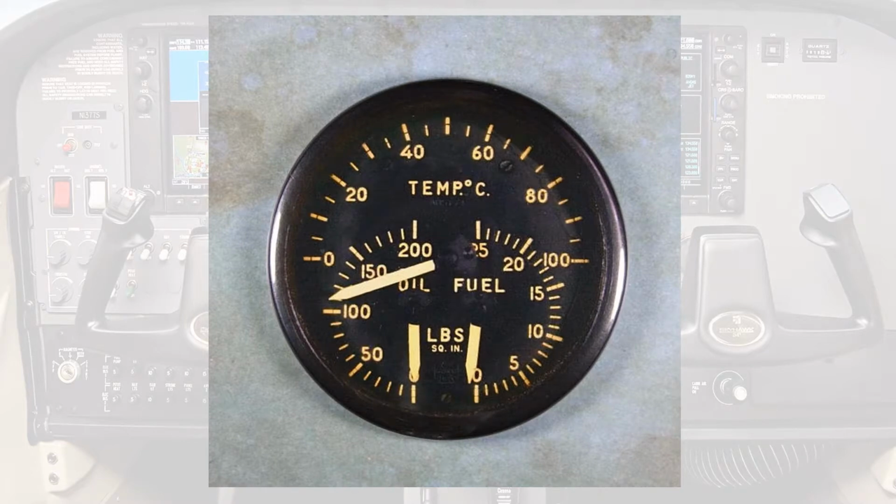Temperature instruments use a thermocouple to measure temperatures. A thermocouple consists of two dissimilar metals welded together, and they form the sensing probe, the hot junction. The cold junction is at the instrument. When the hot junction is heated, a small voltage will exist between the hot and cold junctions inside the instrument. The scale of this instrument is calibrated in Celsius or Fahrenheit.